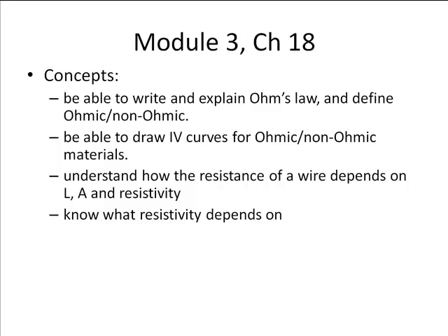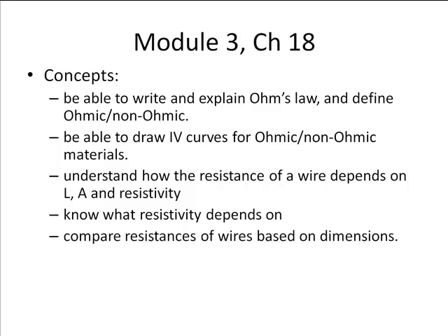Remember, resistance is just like friction. It's the resistance to the flow of charges. So you can imagine that as you increase the temperature or you increase the amount of impurities you have in the material, there's going to be more scattering of the electrons as they pass through the material. So you need to be able to compare wires, and if I give you two wires of different lengths or different areas or both, you should be able to compare the resistances of the wires.